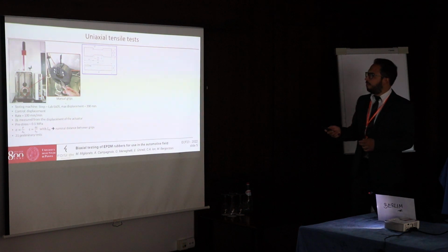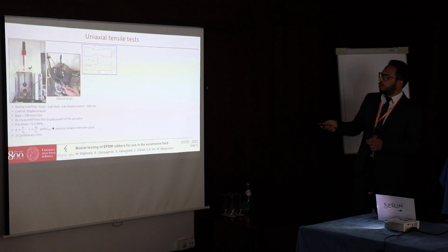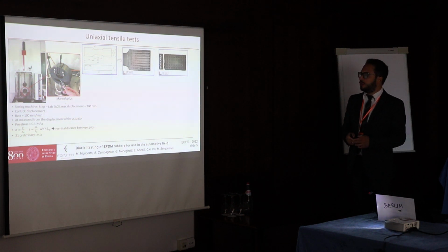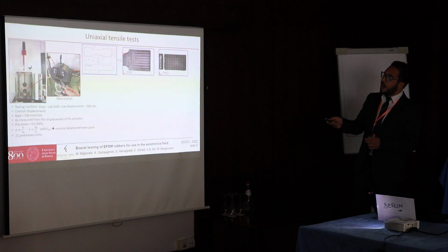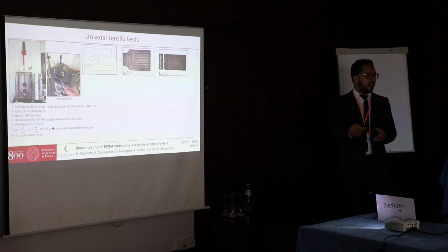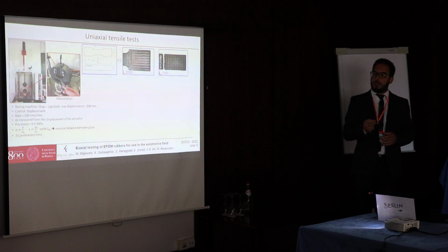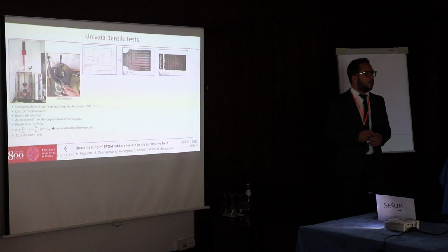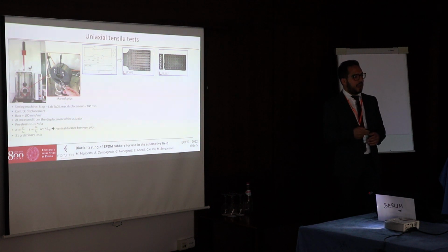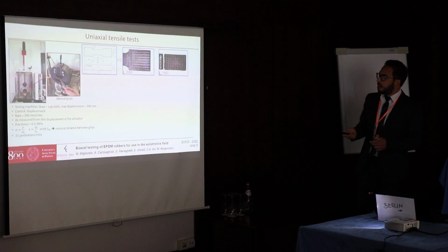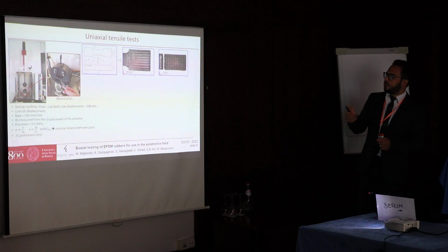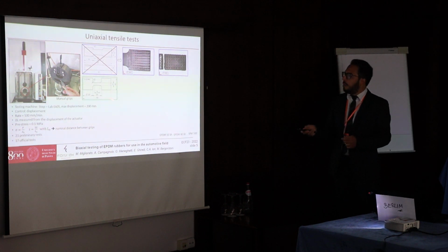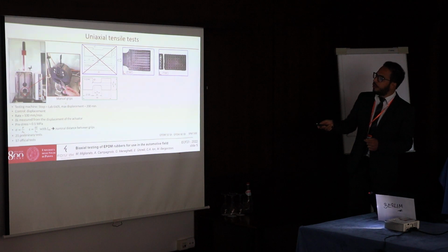Preliminary tests performed on dog bone specimens and also rectangular ones showed a large slippage of the specimen from the gripped area, and moreover, even when the specimen failed, the failure occurred always at the gripped area or at the fillet radius. Therefore, the dog bone specimen geometry has been improved by increasing the gripped area and also the fillet radius.